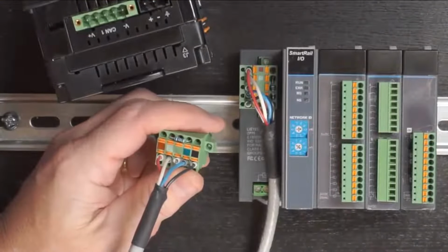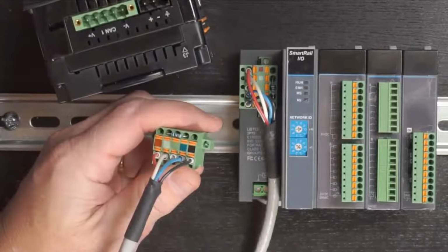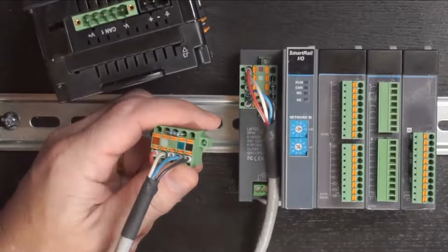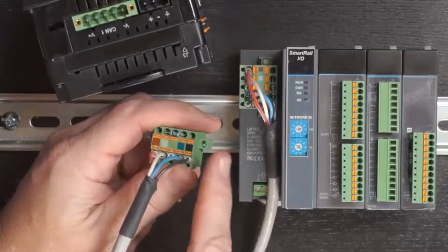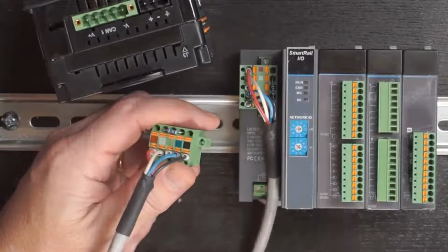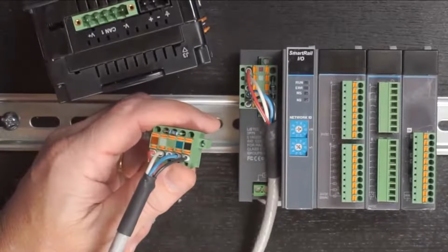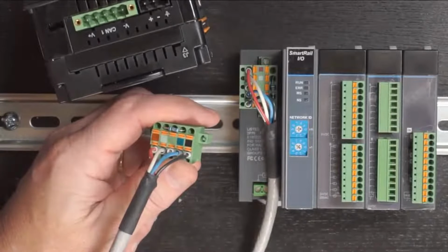Okay, here I'm showing you just a short little section of cable that I made with actual CAN cable. So it's designed to connect an XL4, which I have here, and a SmartRail CsCAN base. So the XL4 comes with one of these double plugs included with it, whereas the SmartRail, as I've mentioned before, it comes with a single plug, this guy right here. But these double plugs are so convenient. So I went ahead and added one as an accessory to this SmartRail. So I've got just a point-to-point cable here using actual CAN cable. This happens to be thin CAN cable, which is good up to 100 meters.